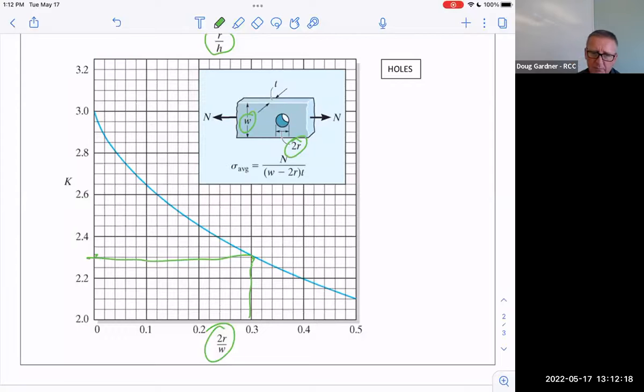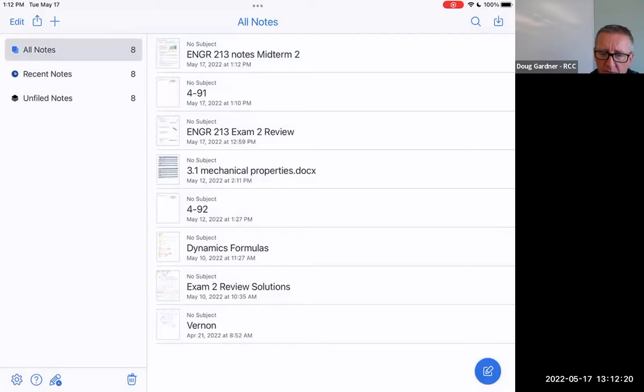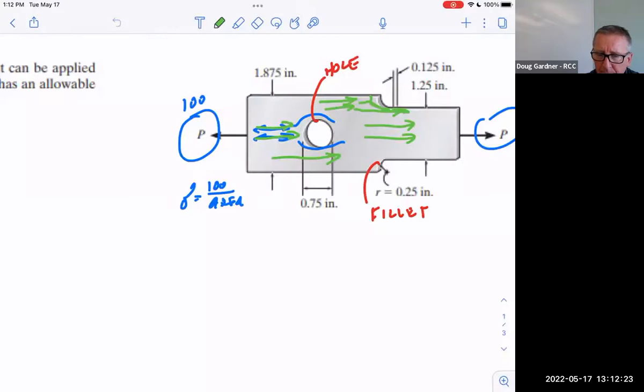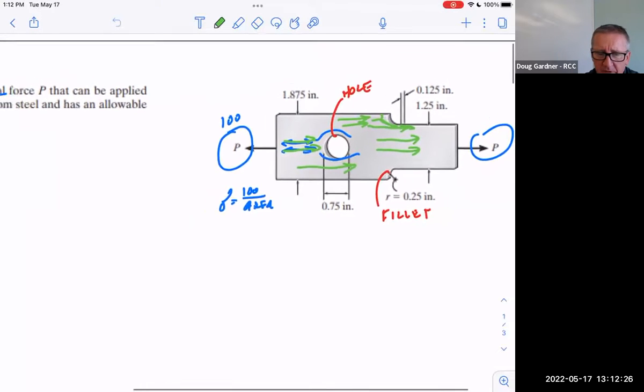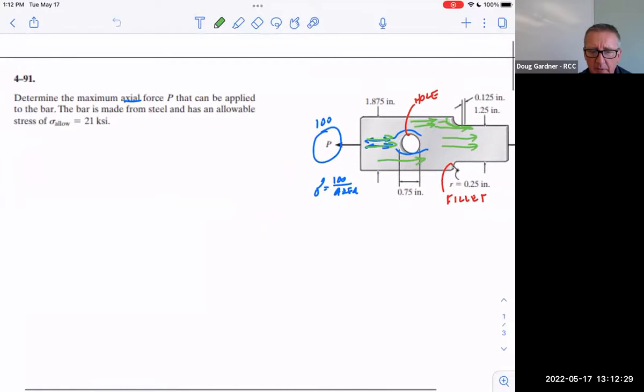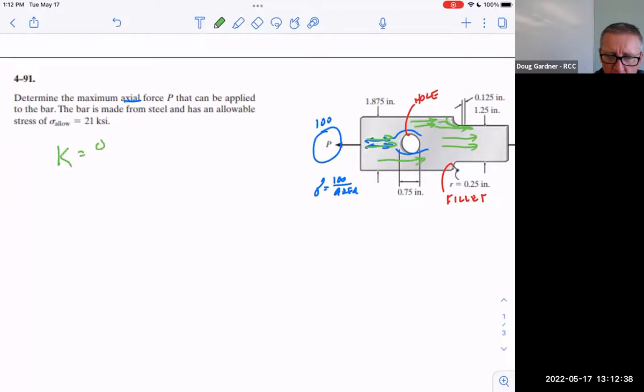And so let's play with that. Let's see if we can figure this out. A second ago, that hole looked simpler to me. I don't know if it looks simpler to you, but let's play with this a little bit. In this case, the main formula we saw on the note sheet a second ago was that K was the ratio between the maximum caused by these stress concentration points and sigma. Before, we always just calculated sigma, which they called sigma average in that formula, but I'm just going to call it sigma because that was the stress we always calculated. So that's my basic formula.